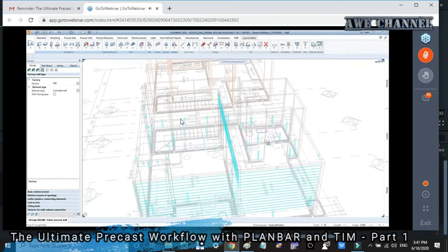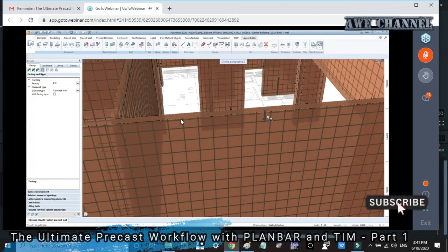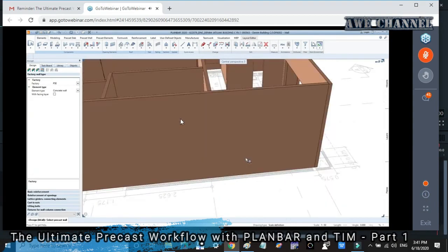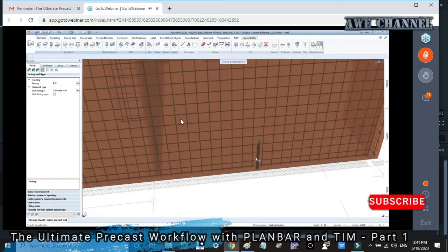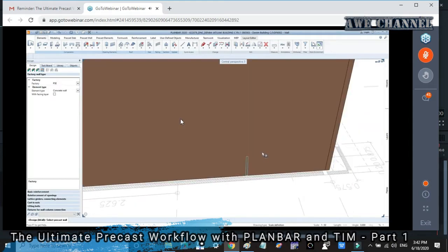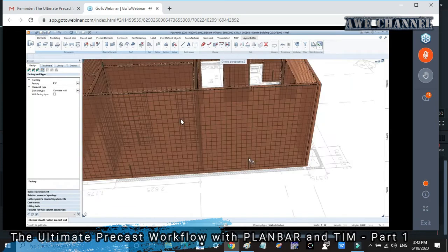You can see now in a few seconds you have listing both, you have reinforcement, you have corrugated pipe, and of course you can set a loop. If you have a fixture or items here, the system will automatically cut reinforcement. It depends on you. We are really open for that. If you don't want to cut out reinforcement because you have a fixture or items here, we are really open for you to customize it.